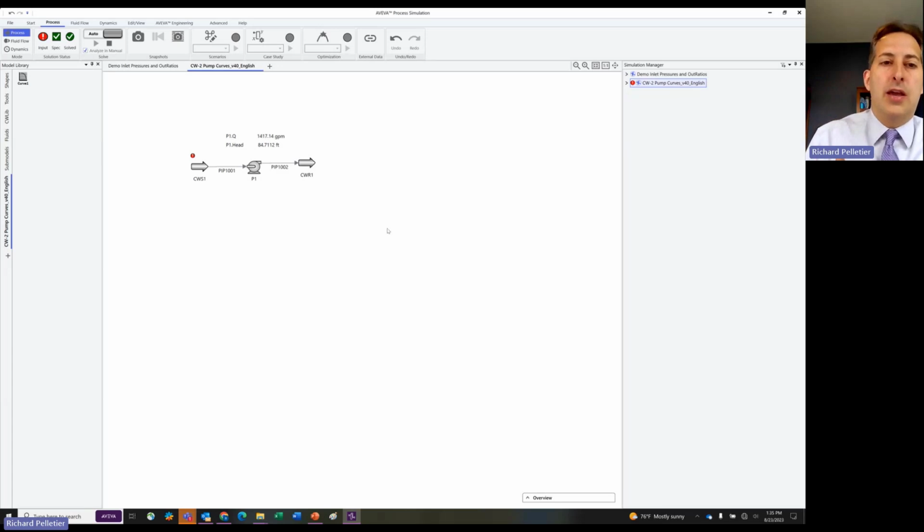You're going to want to create a curve that relates the power to those different properties, right? And then use it within the model so that it has a more accurate representation of the power calculation, right? So this is probably where you're going to end up using this capability, but anywhere where you have some kind of curve or relationship is going to use this same infrastructure to create a performance curve, right?